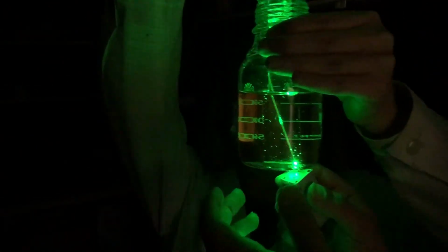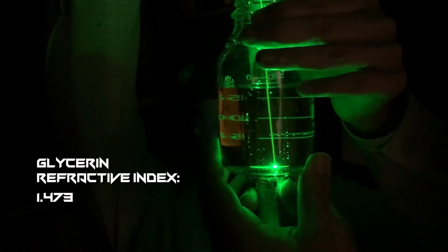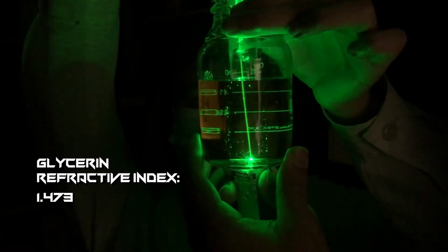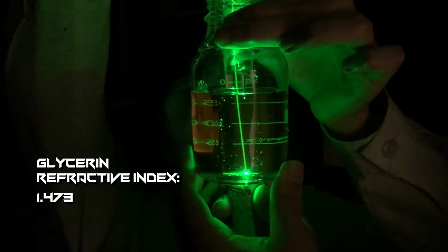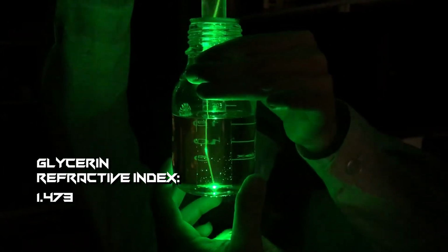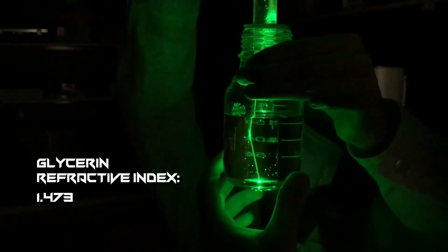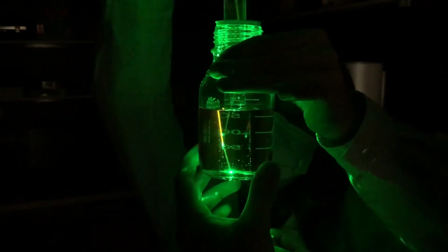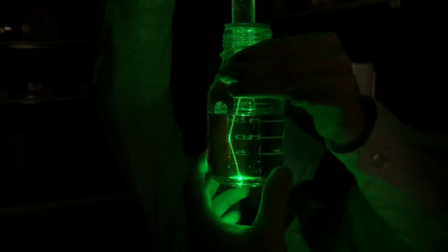After that, the simulated cladding was glycerin, which has a refractive index of 1.473, that is closer to the acrylic that has a refractive index of 1.495. The glycerin had an orange color due to a process that it was subjected to, but it helped to observe more clearly the light scattering. As expected, the incident angle needed to be higher to promote total internal reflection.